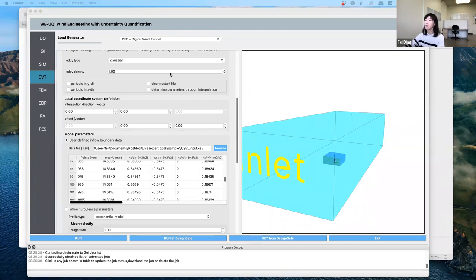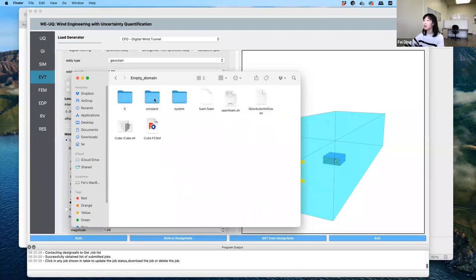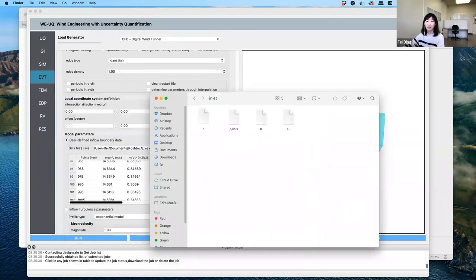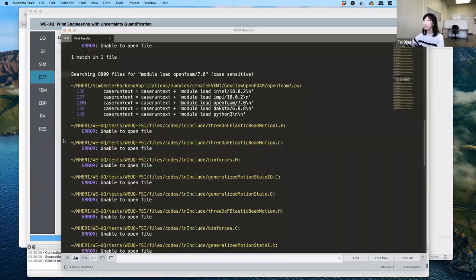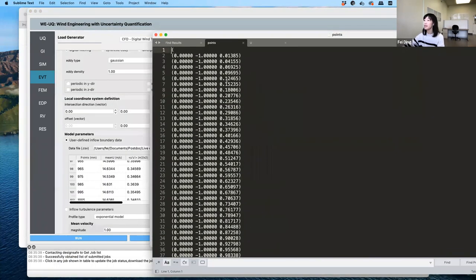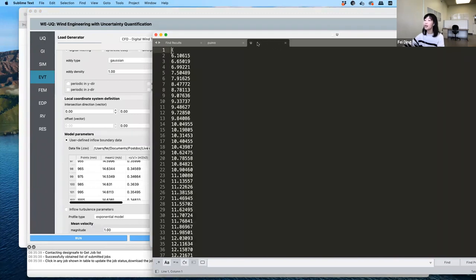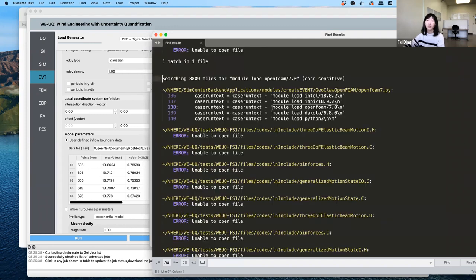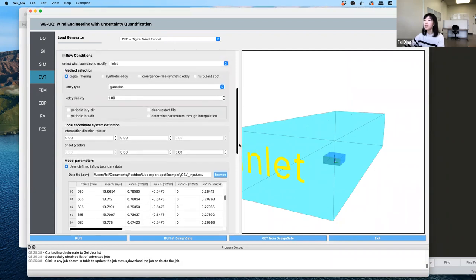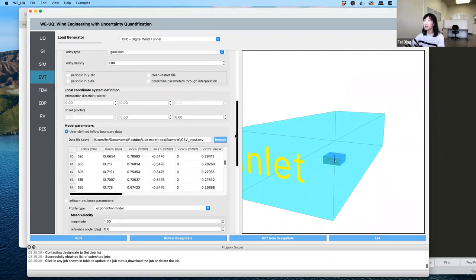Finally, the data will be stored in your OpenFOAM simulations in your constant directory, boundaryData, and you can see this is at different height levels. It corresponds to the table you provide, and also your mean velocity profiles. And after these files have been prepared, the TInF function can be directly called to run the inflow turbulence generation based on the method you select. Here we use a digital filtering method to generate the time histories of the inflow turbulent velocities.